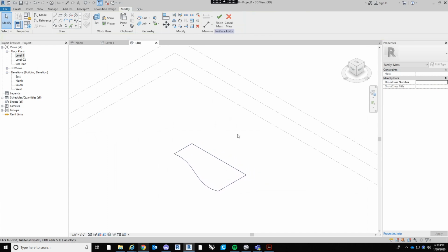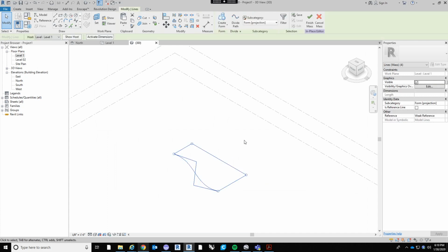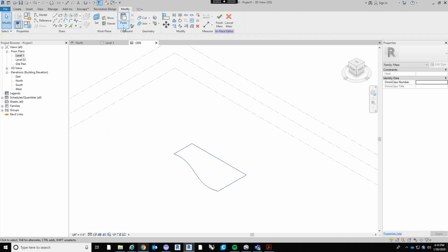All right, and then pasting, you can paste it the traditional way where you just Control V. Oh, this version of copy in the Modify tab is completely different than the Control C copy. All right, so Control C this guy, so it copies to the clipboard. And then under paste there's a drop down arrow. So there's several things that you can do.